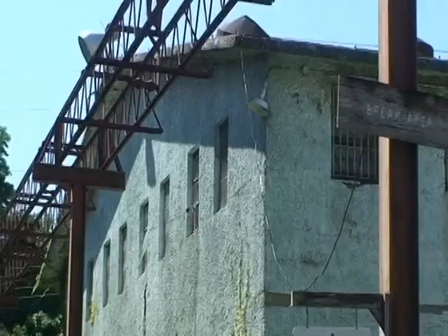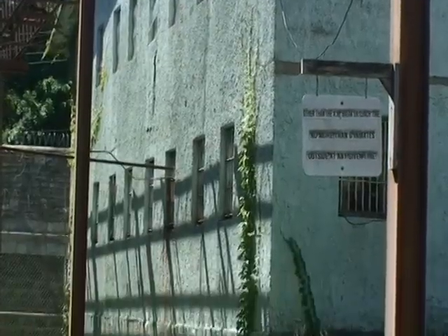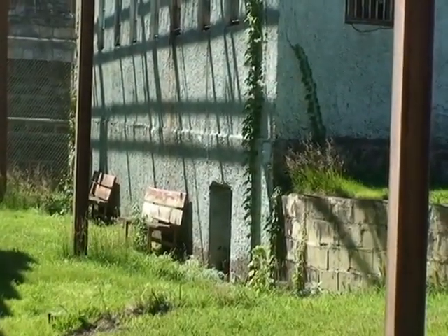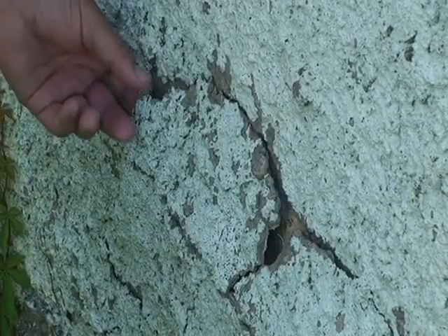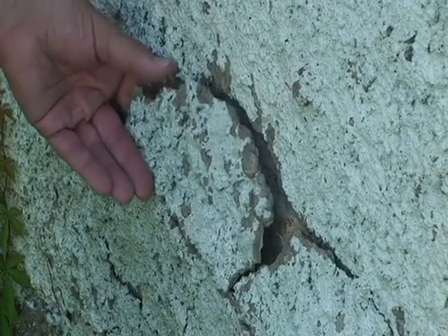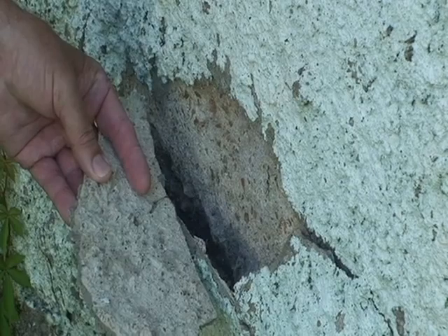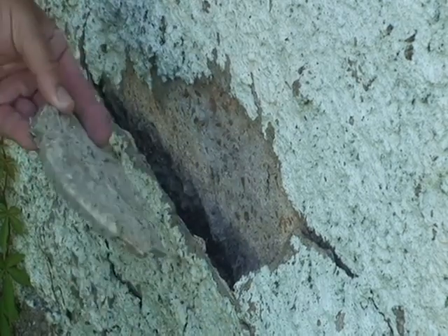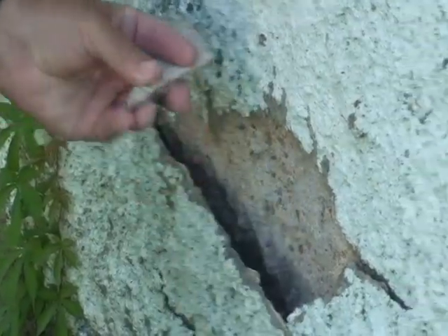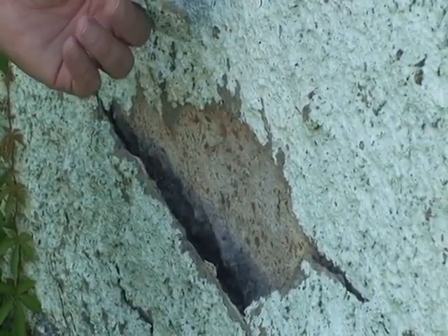Here's another example of surface texture on an interior wall. Here's an example of an exterior plaster with a textured material on it. Textured materials, whether spray applied or hand applied, are considered a suspect material, and those always need to be sampled and characterized accordingly. These would always be considered a friable or a regulated asbestos containing material when they're removed. Here's an up-close example of the texturing that's been applied to this plaster on the outside of this cell block. It breaks easy, and would be considered a regulated material if it was asbestos containing.